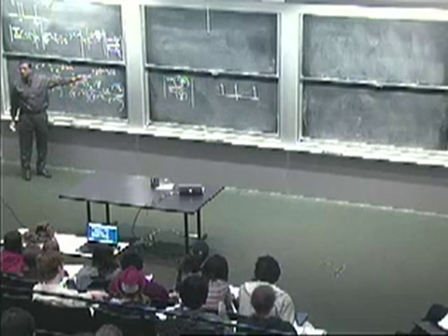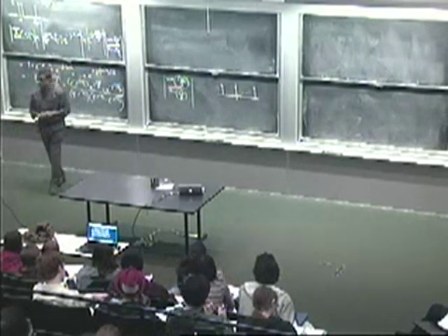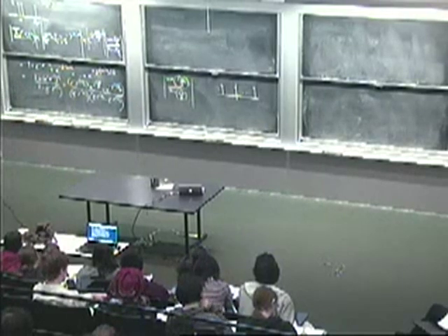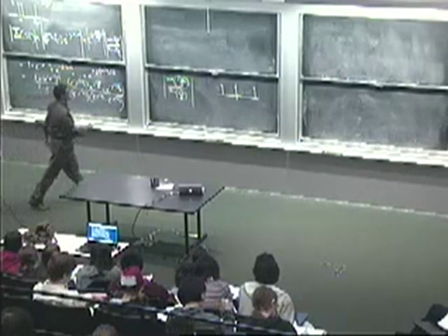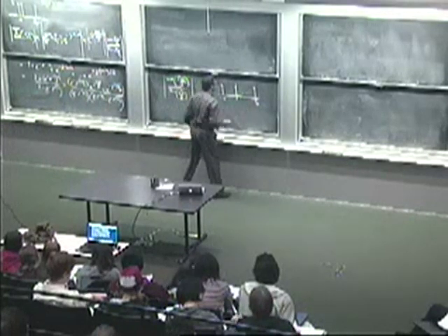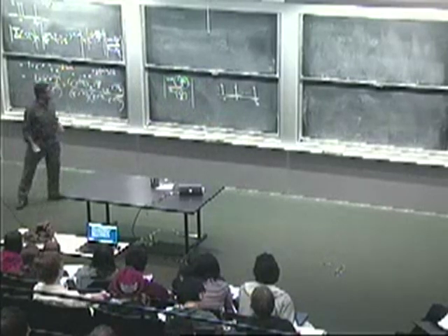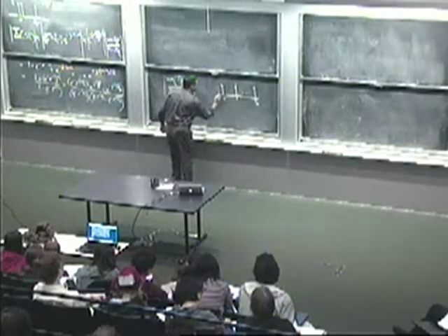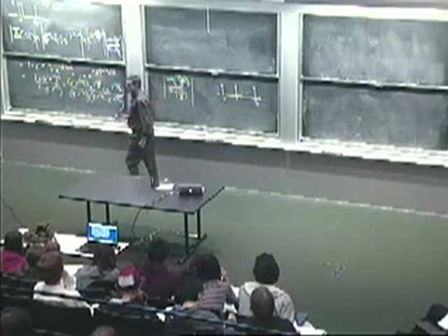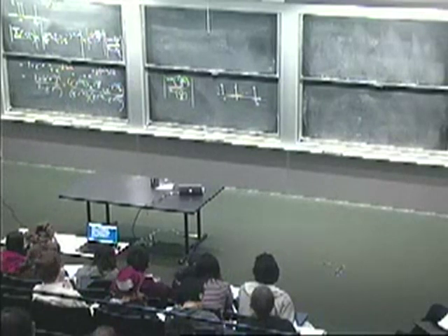And all you're left with is the sine omega n over 2 divided by sine omega over 2. So you're looking at the actual DTFT of a pulse of that type. Okay, so this started at -5 and went to +5 and was 11 samples long and was 0 everywhere outside of that. So that's what this function looks like, the sine omega n over 2 divided by sine omega over 2.